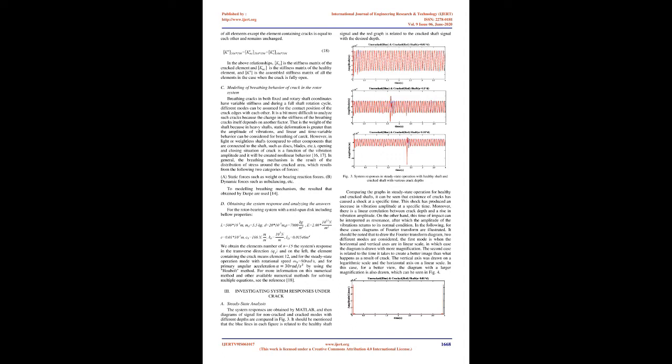Due to the presence of cracks in the rotor system, the stiffness of the system and the system's force vector, as will be mentioned next, are constantly updated and changed with shaft rotation. Conversely, other coefficients, including mass matrices, damping, and gyroscopic effects, remain constant. To obtain the above matrices in the general coordinates of the system using finite element principles, the fixed matrices of each element, disk, and bearings are assembled.